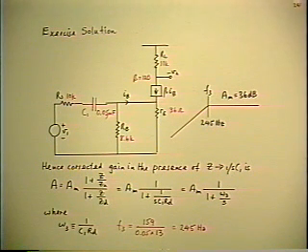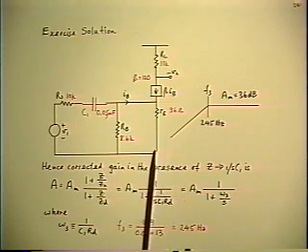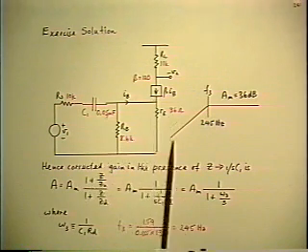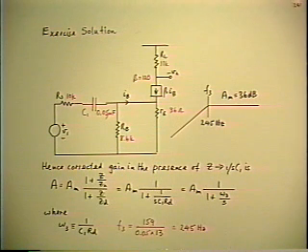The only case where it didn't was the one where the extra element was a parallel R and C, in which case the driving point impedances were still resistances because the reference circuit was resistive, but the extra element was an impedance and not a reactance. And so that required one more line of algebra to get the pole zero form. But that simple case, resistive reference circuit, reactive extra element, is what makes the theorem useful in the other range